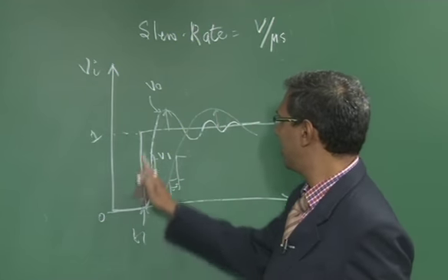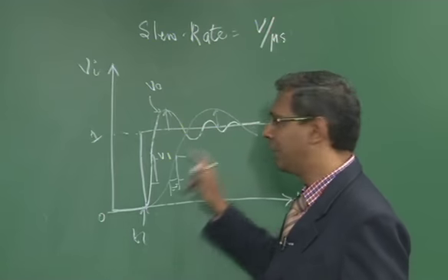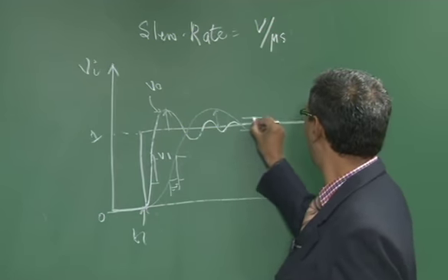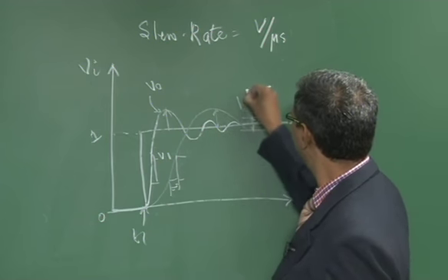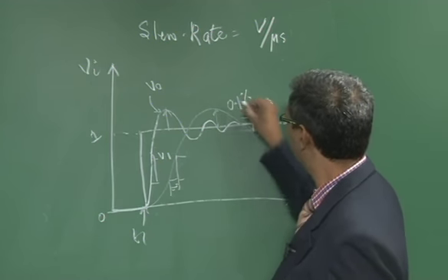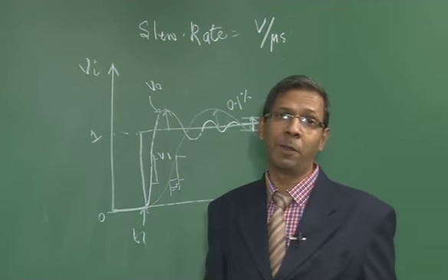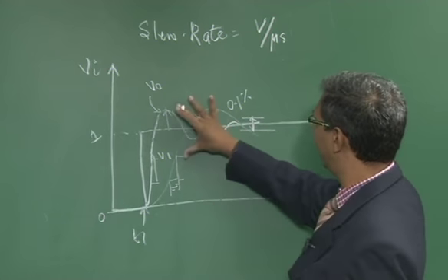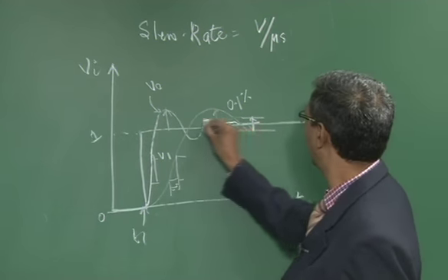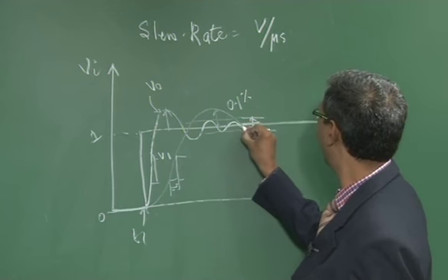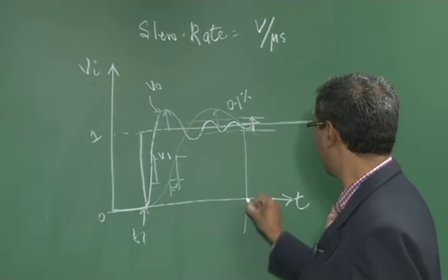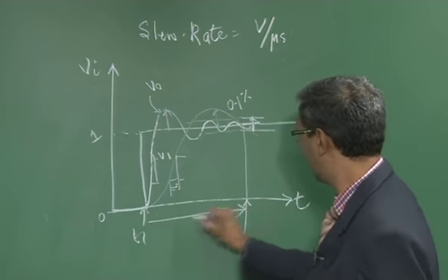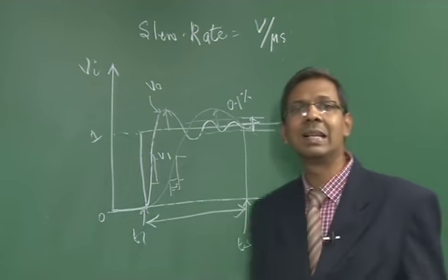In this case, it is expected to reach our output of 1, which is the unit step function that I am giving. So let us say the moment the output reaches within 1% or 0.1% or 0.01%, as the case may be. So it is 0.1% of the range. Here it is beyond the 0.1% band, so somewhere here it reaches this band. This I call the time Ts. So T1 to Ts becomes my settling time.